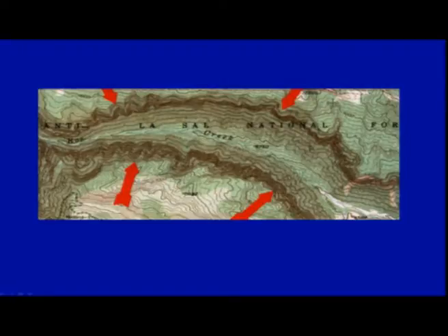If you look carefully at the contour values and the spacing between the different contours, one can make out whether this is the limb or the top. Here they are very closely spaced, whereas here they are slightly more widely spaced. So these are the escarpment or the limb of the fold, and this is either the top or the basin part.